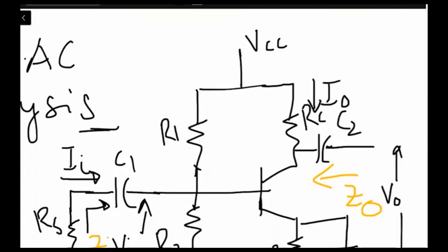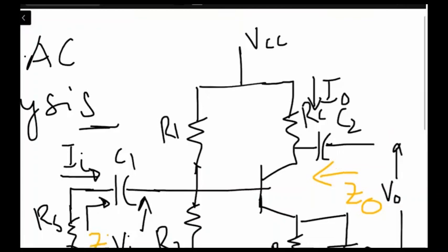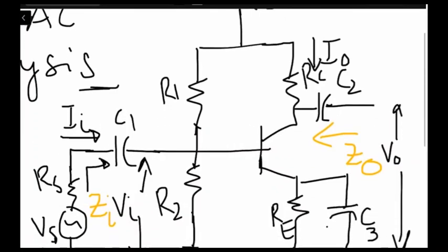So first we need to get rid of the DC components in the circuit, right? If there are two biasing sources, let's suppose VCC and VEE, we need to remove both of them, because we have already utilized their usefulness by obtaining the Q point.